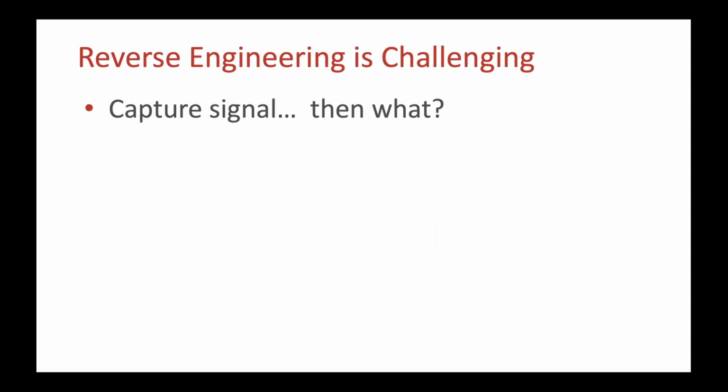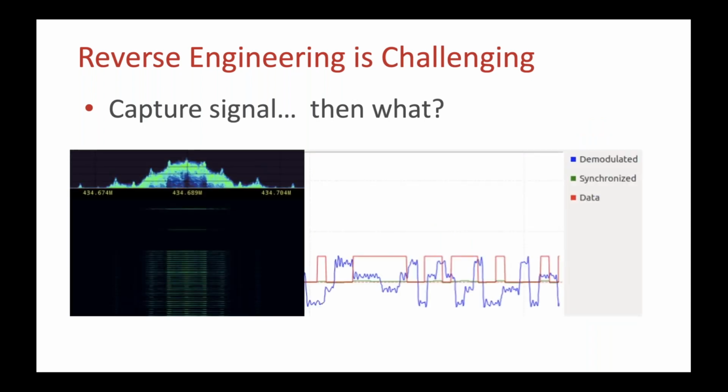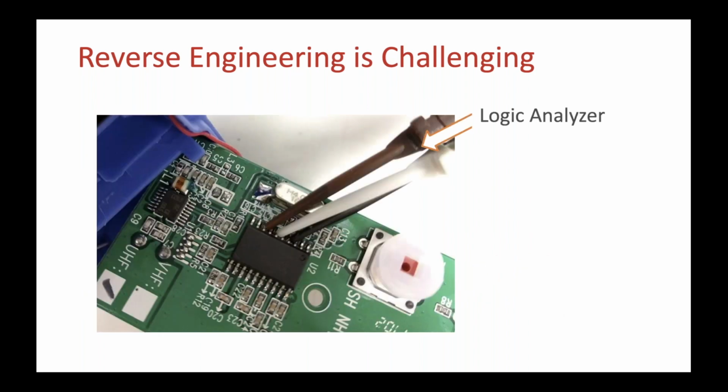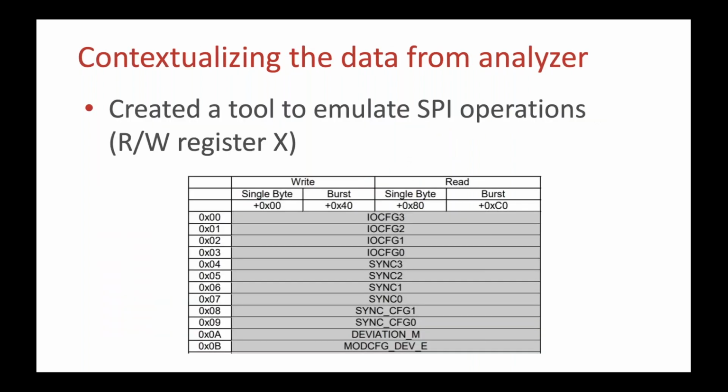So we captured the signal, now what? Then we decided that we were going to hook it up to a logic analyzer to try to clean up some of that noise. We specifically used a tool to emulate SPI operations with read and write registers. So we created a tool that emulates the SPI.